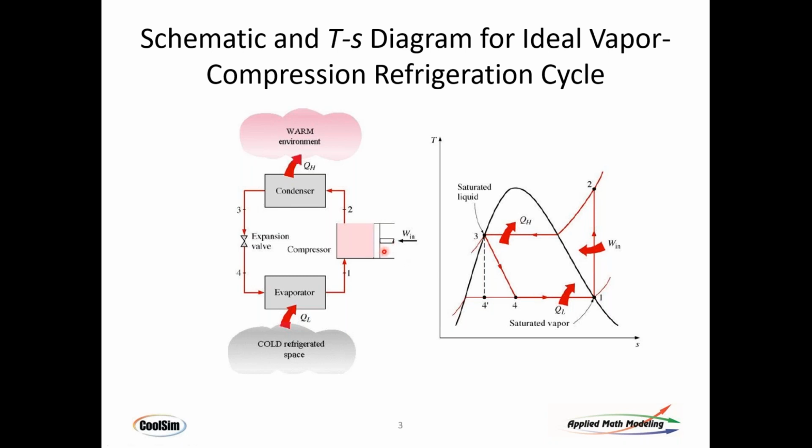What we do in data centers and so forth, even air conditioners in your home, I'm going to start here with the compressor. So here's the compressor, and we're squishing a medium gas. Of course, the ideal gas law says that if you squish the gas, it gets hot. Once the gas is hot, it goes up into the condenser and gets dumped to the atmosphere through a heat transfer process. Now, in a DX system, this heat transfer, which is also over here on the Rankine cycle happening right here. So here's the work going in, and it's raising the temperature until that medium gets to a very high pressure point and becomes liquefied.